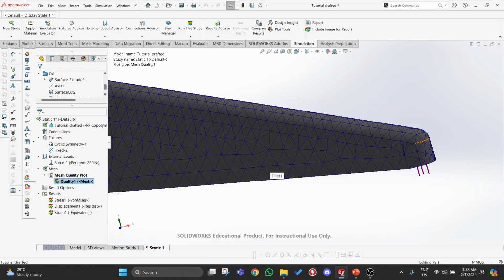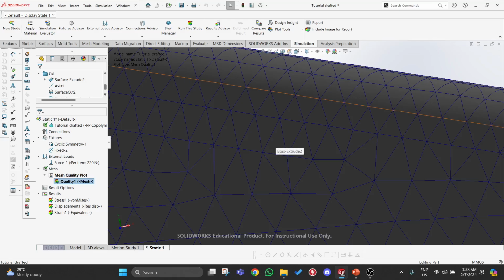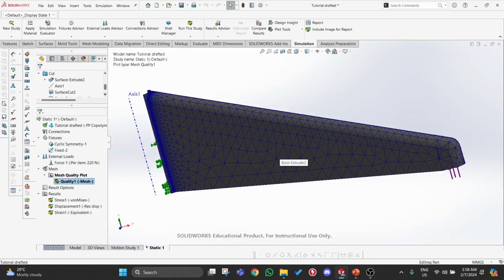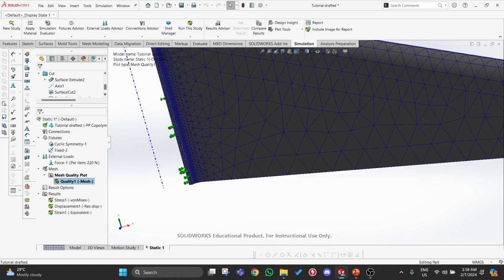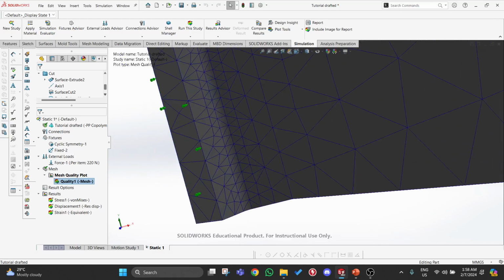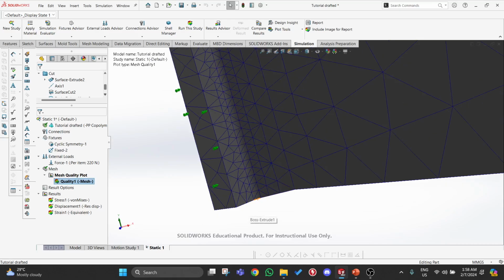And what does that do? Your value does not even out over a large area, because it's calculating the force on this entire triangle. So that's why you need local mesh refinement, and local mesh refinement is only possible when you know where the issue is.